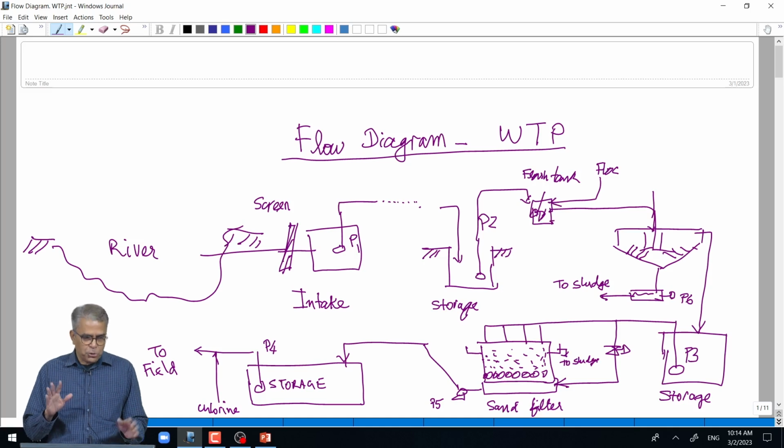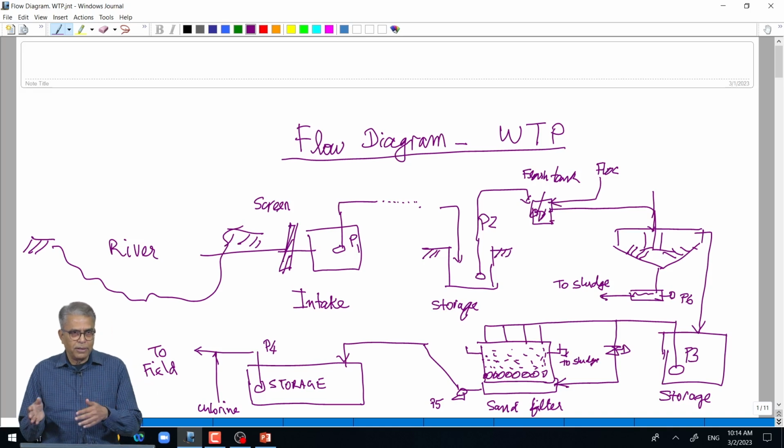So, I have shown here some river, and normally if it is a river, you cut a channel from the banks of the river and take that water, create a mini river kind of a thing, and the river surface usually comes with all sorts of rubbish. So, you put a screen and the screen will filter floating gross objects and it should not get choked. So, you have a continuously travelling grate. This filter kind of replenishes the surface, it is a very interesting kind of a filter.